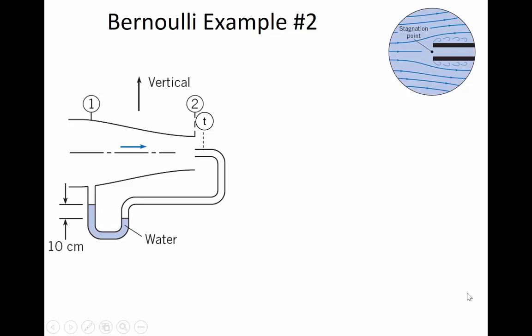So in other words, the energy along the center line, we're going to assume that the energy is constant. Remember, we've got this magical inviscid fluid where there's never any energy losses. Because it's inviscid, meaning it has no viscosity, that means that it never loses energy due to pipe friction. Now, of course, there's no magical fluid that's completely inviscid, but as long as we apply Bernoulli's equation between 2 points that aren't too far apart, then there's going to be so little energy loss that we don't have to sweat it.